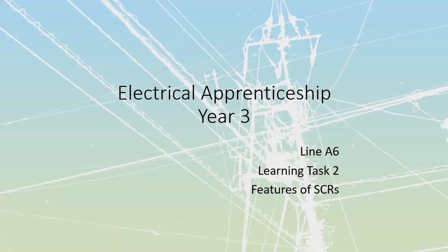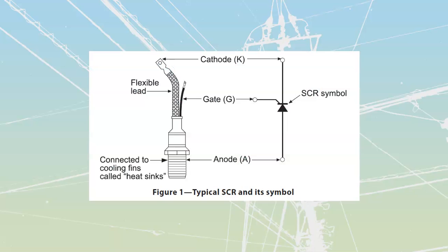They are unidirectional. Just like our diodes, they are only going to allow current through in one direction, but they're going to have 3 terminals. And in a lot of ways, we are going to see these things as being controlled diodes. We call these things the silicon controlled rectifier. It has this one terminal down over here called the gate, which is going to allow us to put this thing into conduction, and then it is going to stay in conduction until it reaches a certain other value of current, which is going to be its dropout value of current.